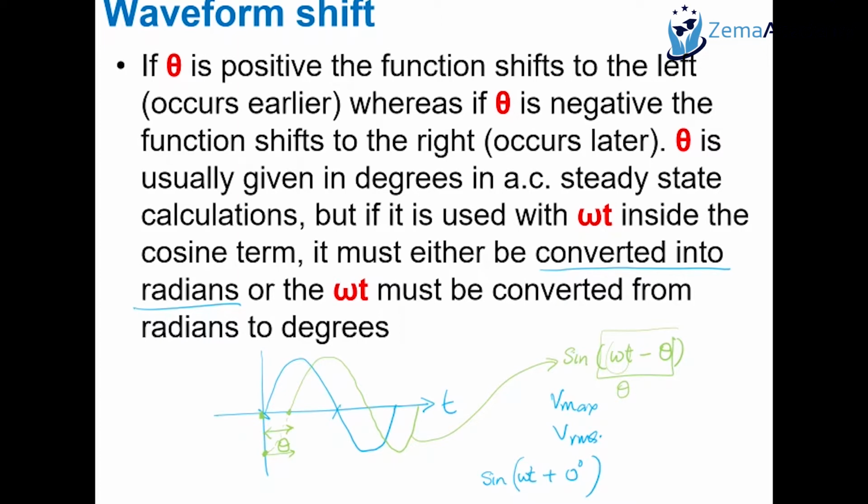So this is what we call the lag. And the other one, where you move this way, you call leading. The values of angles you show here are one convention. And whenever you have a lag, although the angle is given as minus theta, you just take the theta and you do cosine of the theta to give you what we call the power factor. And that power factor is referenced to be positive. All lagging power factors are indicated as positive power factors.